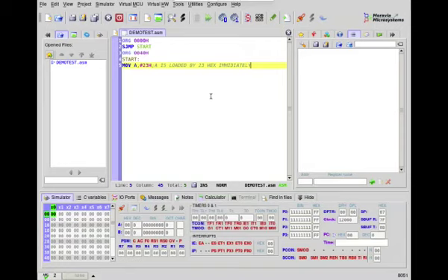If I am not writing H after #23, the meaning is 23 decimal is loaded in A register. So I am writing this.